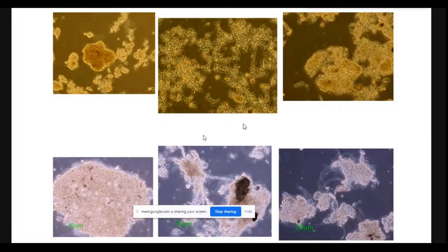But otherwise, these particles will remain in suspension in the primary treatment. So we need to have this understanding in the primary tank that as much of the solids as can be removed by settling in the gravitational tank, we must be able to remove. Just by a natural gravity process, these particles will not get settled at the bottom, for which you require a pressurized air injection to see that these things are broken into small particles, and then apply coagulant, and then try to bring down the particles before you apply the aerobic treatment. So I'll just show you how these things actually look in any domestic wastewater which enters into a treatment system.